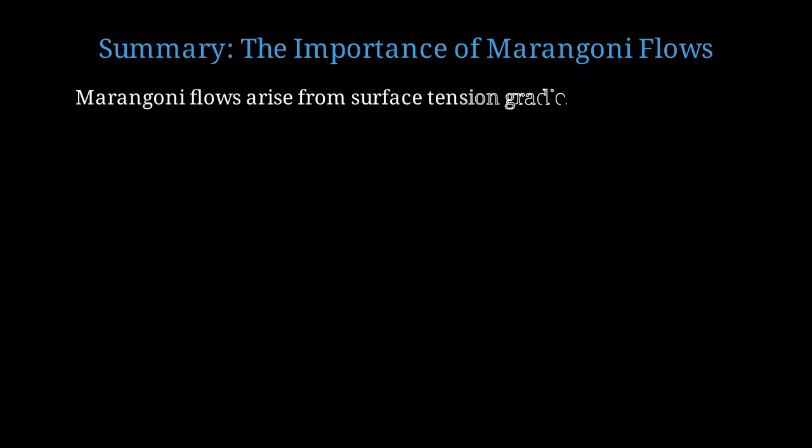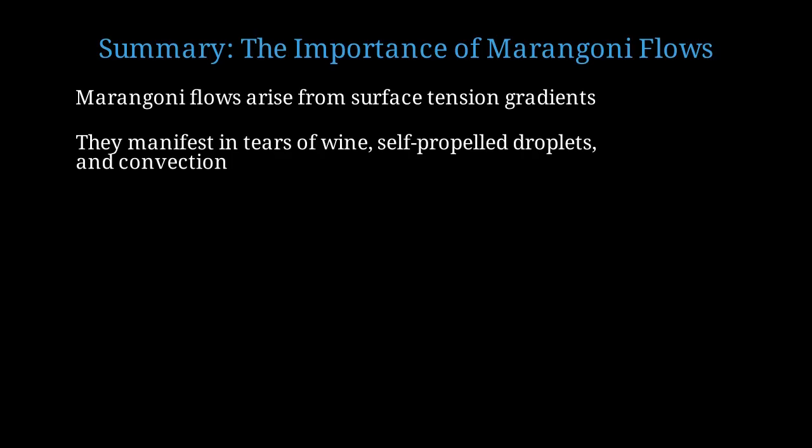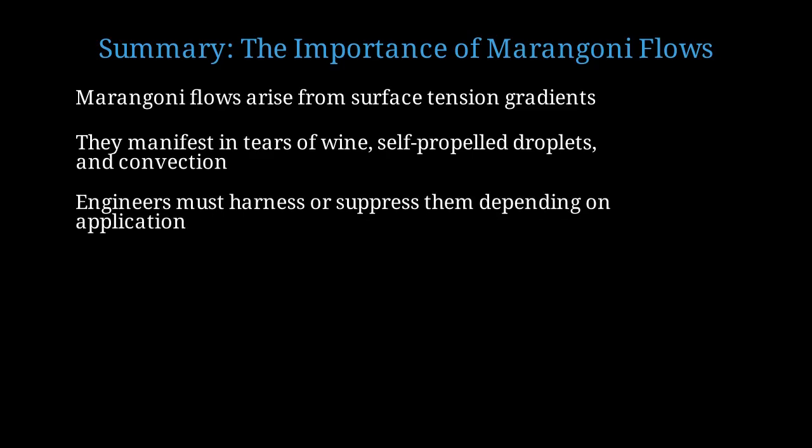Let's summarize what we've learned about Marangoni flows and their significance. Marangoni flows are driven by gradients in surface tension, which can result from temperature differences, concentration gradients of surfactants, or compositional variations. We've seen how Marangoni flows manifest in phenomena like tears of wine, self-propelled droplets, and Bénard-Marangoni convection cells. In engineering applications, Marangoni flows can be beneficial, as in microfluidic pumping and weld pool control, or detrimental, as in